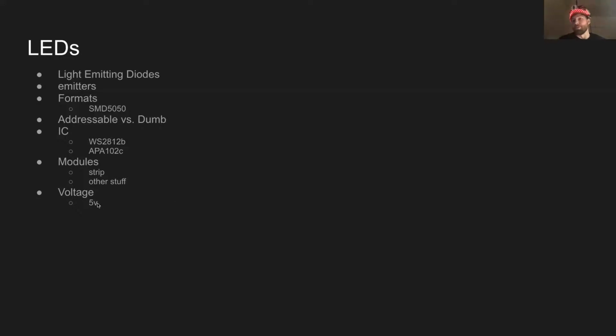Lots of things, like your cell phone, get charged at 5 volts. This is a very, very universal conventional voltage. These operate at 5 volts, so you have to provide them with exactly 5 volt power. It's very nice to work in 5 volts because if the LEDs run on 5 volts and your controller also runs on 5 volts, then you can simply have one power source, one power circuit powering everything, and you don't need to worry about supporting multiple voltage levels in your system.